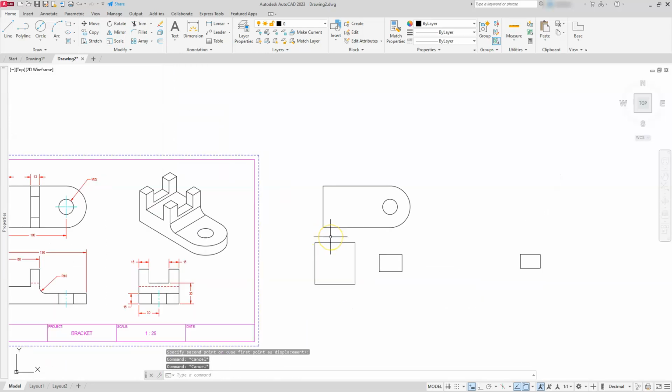Next thing we need to do is make sure that each one of these is going to be a closed polyline. So you can see that the rectangles that I created are done with no problem. And what I mean by closed polylines is that if you select one of those rectangles or objects, all of them will light up. This one along the top are individual lines, so I'm just going to select them all. And then I'm going to go J, enter. And that J stands for join, as you've seen. But if you're an icon person, the join command is located at this location. Alright, so I want to just verify that that is a closed polyline now, and that circle, all circles are typically closed polylines. You don't have to do anything to those.